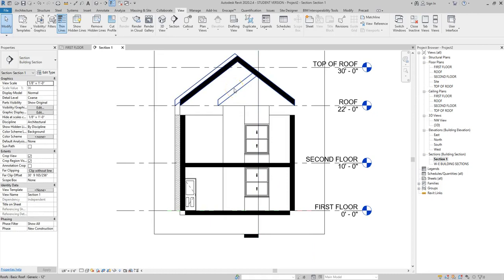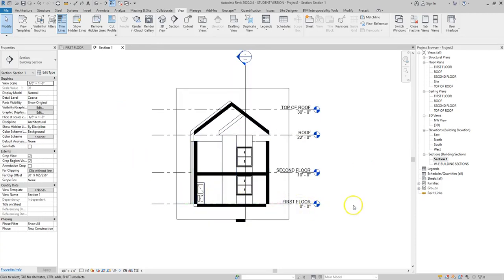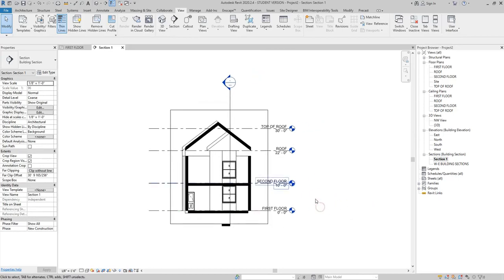Here we can see the roof beyond, so that's why it's not poched. And then we can see that one wall that we had attaching to the top base, whereas the rest of them have not been brought up to the roof yet. So these things are important to think about as you're starting to look at the building in section, and it allows you to start to understand the importance of sections in helping you design, not just in showing information to clients and to contractors.